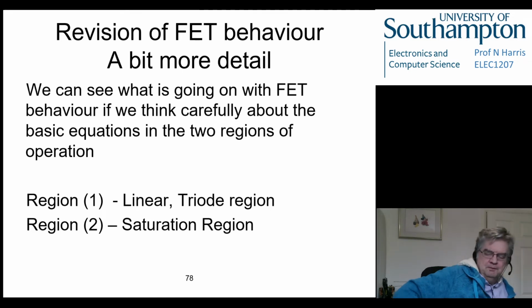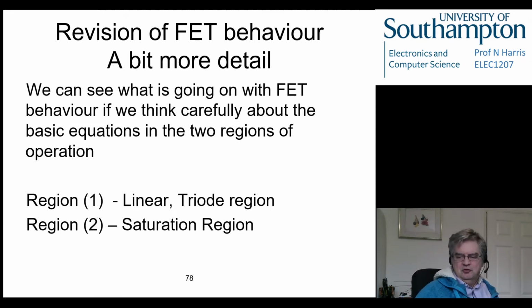Right, so that's all good. It applies, so you can see how a lot of the bipolar stuff that we did starts to apply to the FETs as well, which is quite nice. But we have a slightly simpler small signal model because we don't have to worry too much about R-pi because one doesn't exist. Right, so let's revert back to having a look at what's going on in these FETs.